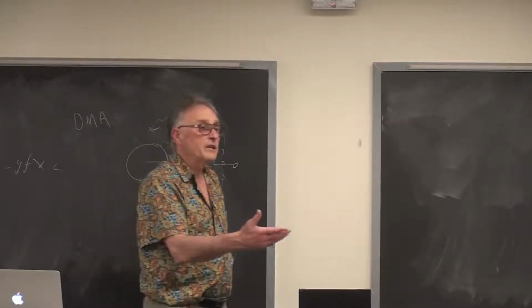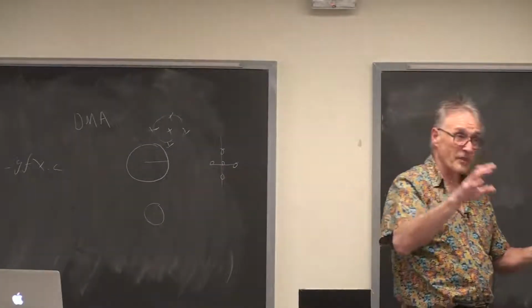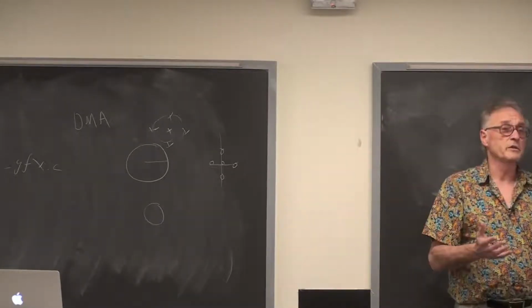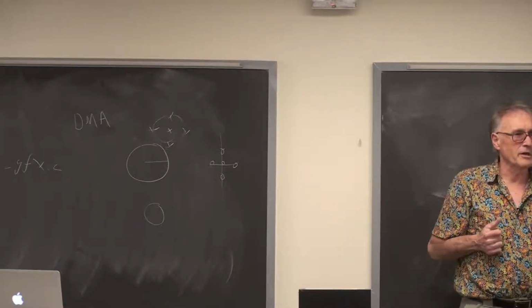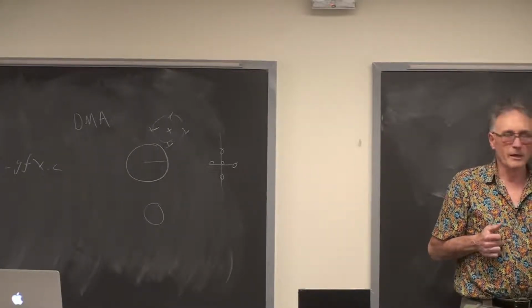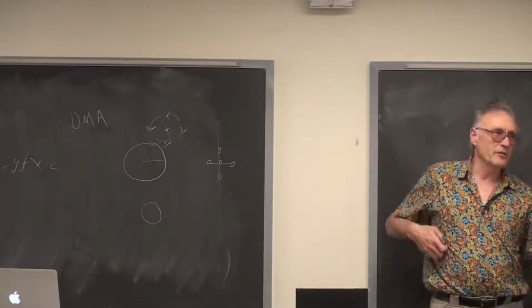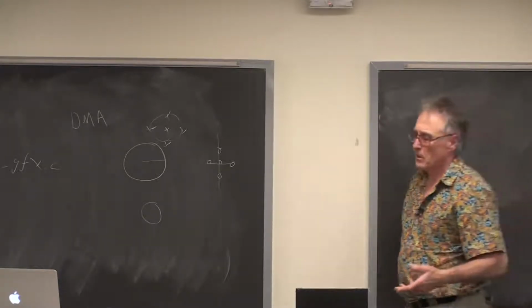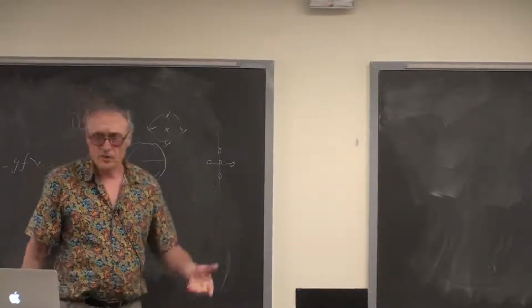Because then you're not having the circle algorithm calculate the offsets of everything, which is doing some sort of numerical integration. Right? It's doing what's called, here's a term, how many people have heard the phrase digital differential analyzer? Nobody. Right? It's operating a digital differential analyzer, which is a primitive form of numerical integration. And it is therefore slower.